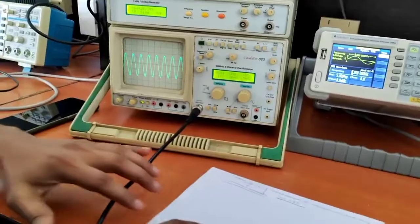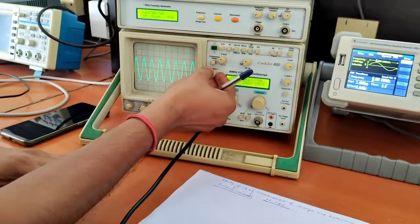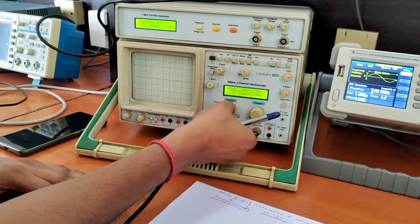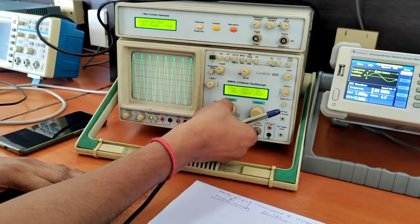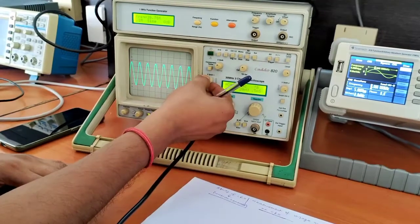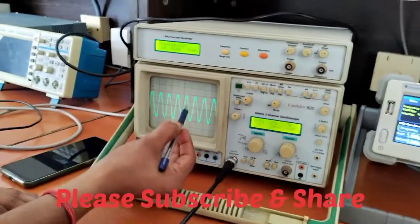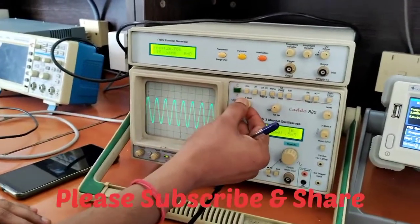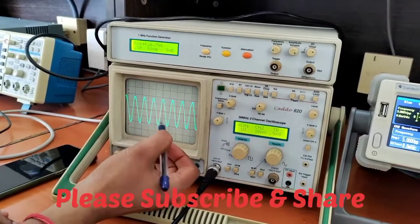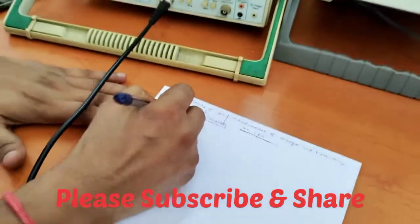Now we can count the number of divisions. The CRO display we have to fit on the screen, so if it is bigger, then we have to fit it. Let's say we fit it. Now we can count the number of divisions. This is one full division, 1, 2, 3, and this is 3 point, we can horizontally shift it, 3.8. So the total number of divisions in peak to peak is 3.8. So we have to write it: number of divisions.